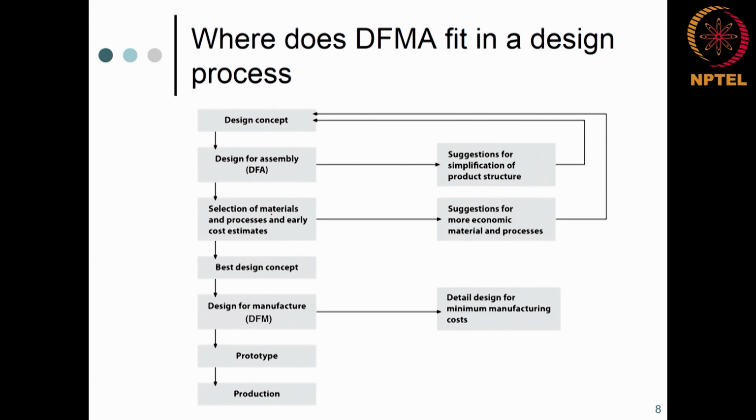Okay, this is something that we don't teach upfront in the design part. Design for assembly needs to come upfront. How are you going to assemble it? Based on that is what I am going to choose my material, because not all types of materials can be assembled on all types of materials. It becomes very important what is going to sit on top of what and what is going to sit under what.